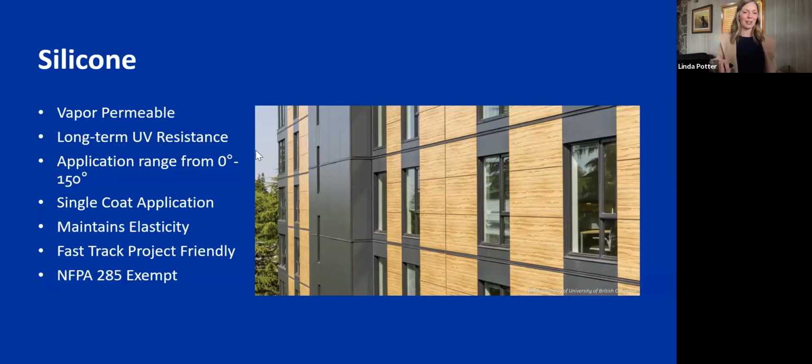That's what we know about silicone. Silicone is tried, true. We trust it as a construction industry. It moves, it's long lasting. So having an air barrier that's made out of that, when we understand how critical it is to the long-term success of a building staying thermally efficient and reducing those heating and cooling costs, that makes sense that we would want to wrap our building in that.